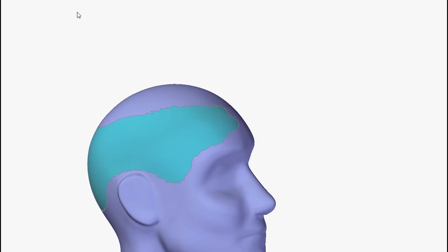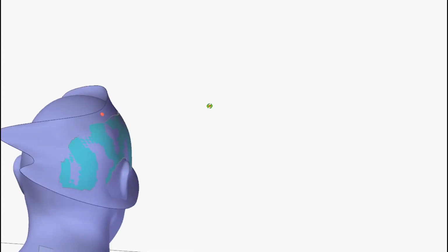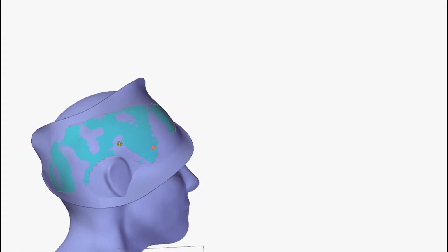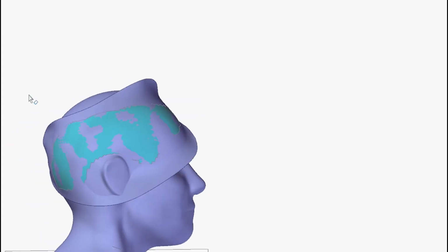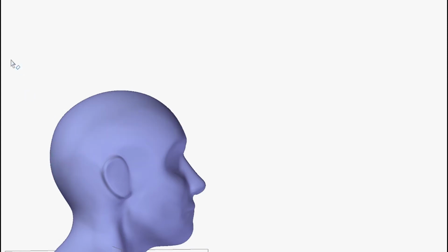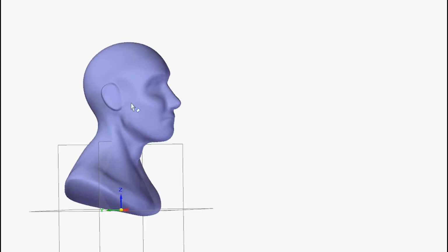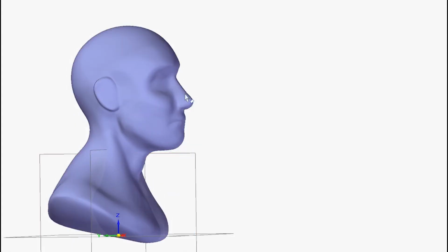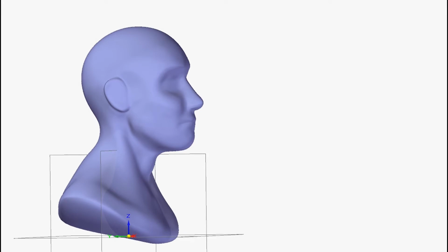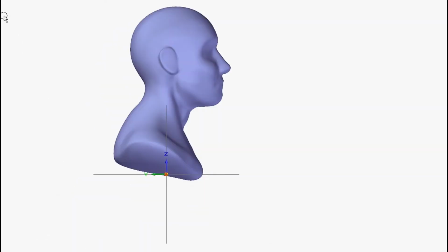And then I'll go to the fit command to capture this region I just created. I'm going to use a B-spline, and then you can see how it goes and captures this little surface that I created, the region I created. But since I already went over this in our previous video, this time I'd like to take a different route. I'm going to be using the delete mesh command. And since I don't need all of this area in the bottom and his face, really, it's going to be a bit cleaner to use this method. It's going to be less crowded.